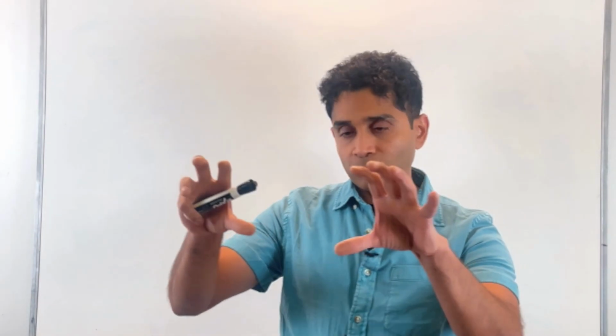The flip-flop is applied a clock, and when we talk about a level triggered flip-flop, for example a high level triggered flip-flop, only when the clock signal is high does my output see the input. Or in other words, my output can respond to the input. As long as the clock signal is low, my output does not even see the input, so even if there are changes on the input, there will be no changes on the output of the flip-flop.